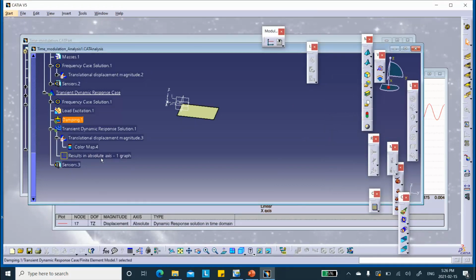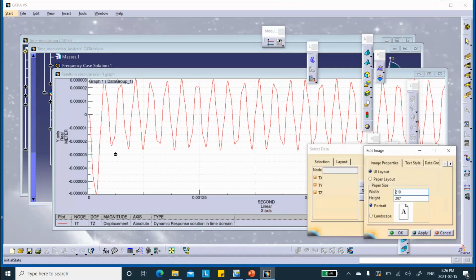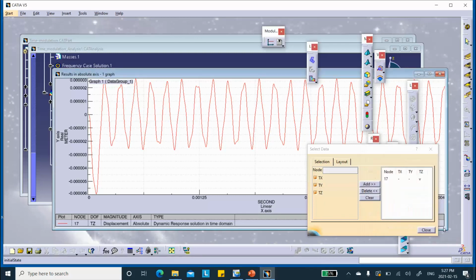And let's see, we have to run it or whether this is going to do the job. Yeah, so you don't have to run it. The reason you don't have to run it is that this is modal superposition. The only thing that you really needed were those natural frequencies which were extracted, and changes like that do not change the natural frequencies. It just changes the stuff that you do in Duhamel integral or convolution integral or modal superposition. But the point is that look what happened.